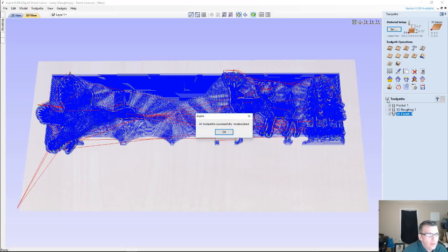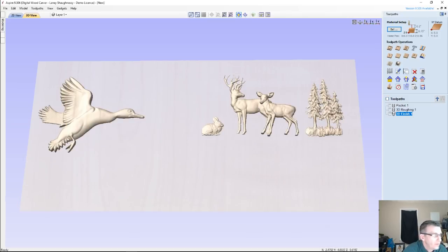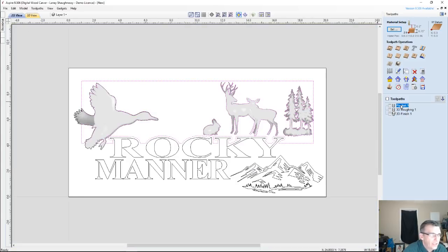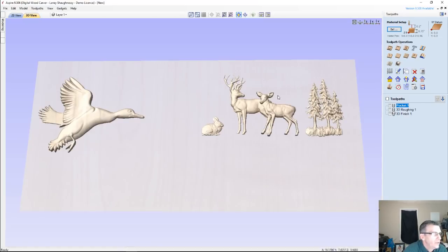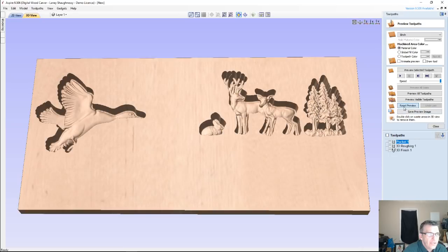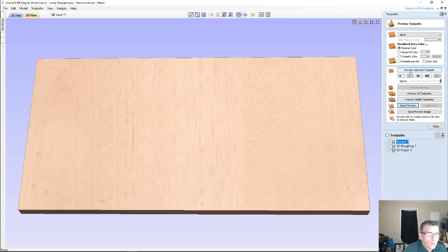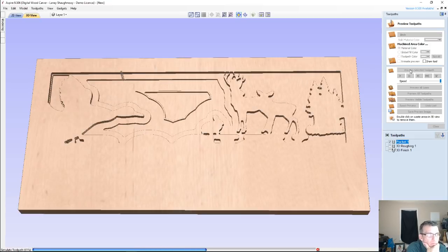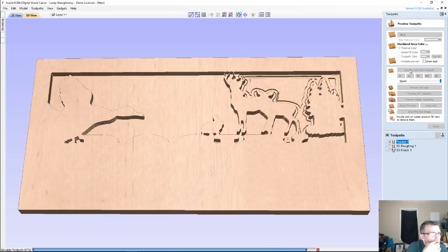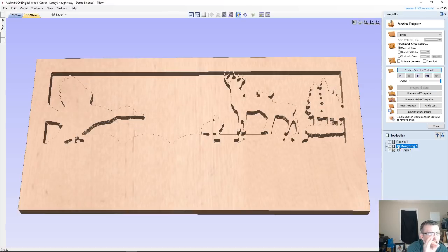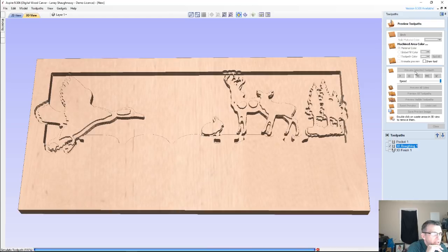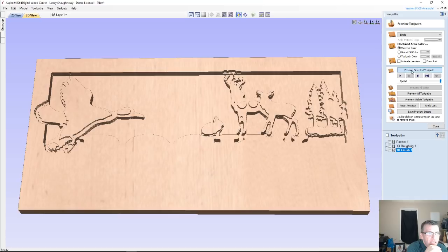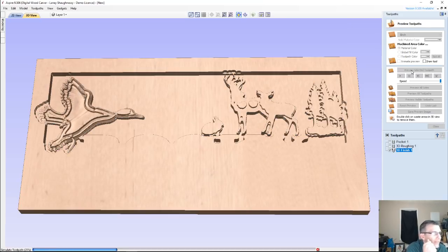As far as missing the bottom left corner, Dave, when I'm doing the model boundaries for the 3D model, I don't need the bottom left corner unless I miss it on my actual pocket cut. Let's reset this preview. We should look a little more normal now if I preview that pocket cut. There should still be a light amount of 3D rough cutting, just a small amount of that, and then my 3D finish should come in and finish.